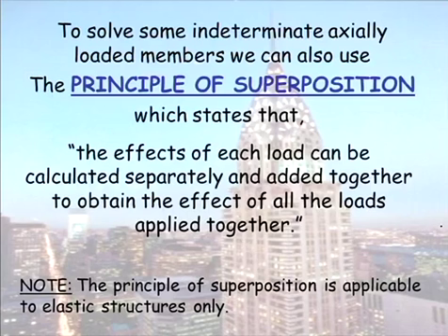So now I'm going to show you the same thing, and when I just explained using that method, I was going, oh, it's absolute values, don't worry about negative signs, don't worry about positive signs. Slightly confusing for me to explain it to you. When we look at superposition, we can actually see what's happening, so we don't have to pretend or forget about signs. So remember, what is the principle of superposition? It states that the effects of each load can be calculated separately and added together to obtain the effect of all the loads applied together.